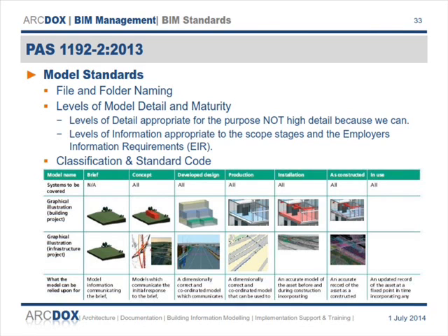This one here refers to the overall maturity of the Revit model. Okay, so in that Revit model, if you're working from an in-house library, you're going to have objects that you're putting into that model that are fully detailed, fully worked out, fully spec'd objects, because you're not going to downgrade them just to put them into a model that's only required for LOD 3. Other items in the model might be much simpler than that. They might be just a rectangular box that says it's a boiler, but you haven't yet developed that up. But the overall level of model maturity is at developed design stage.